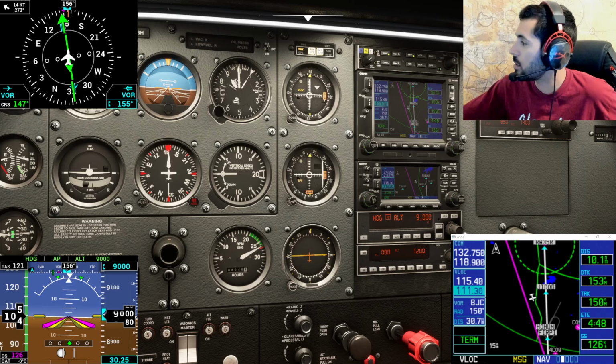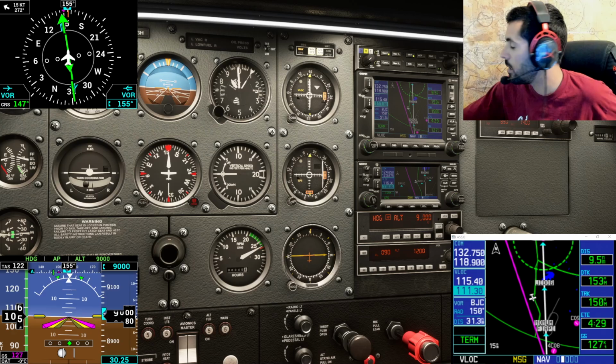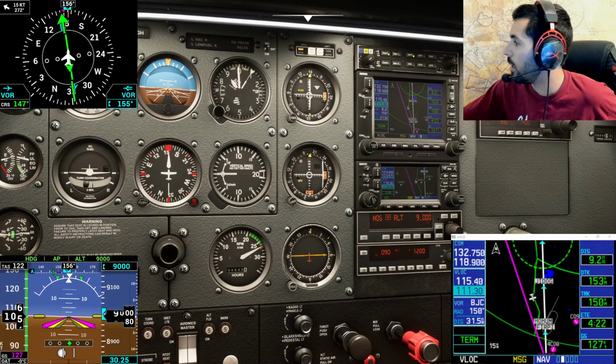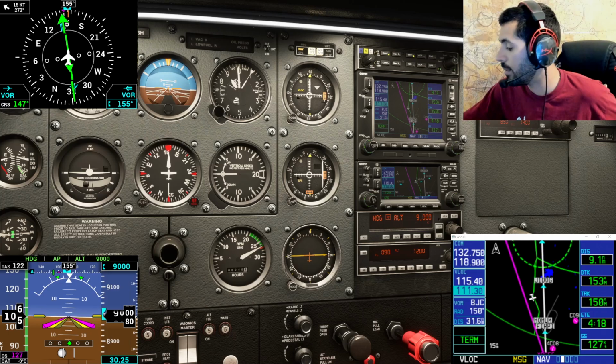That's just a holding pattern. And typically, yes, that holding pattern is on the 197 radial, Falcon. And once we see this, we'll know we're at HOHUM. But we really got to get to XB, which is actually further south. So essentially, we'll kind of hit that radial and continue south, kind of like I want to say 170, and then we'll loop back around.